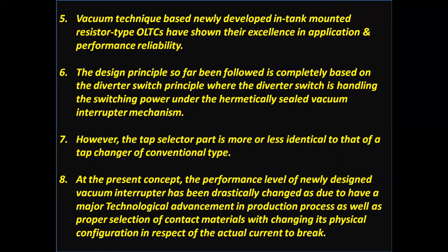The design principle is completely based on the diverter switch principle, where the diverter switch handles the switching power under the hermetically sealed vacuum interrupter mechanism. However, the tap selector part is more or less identical to that of a conventional type tap changer.